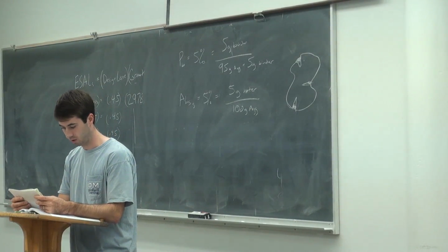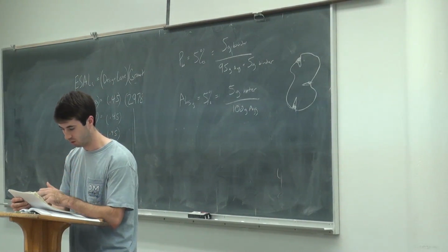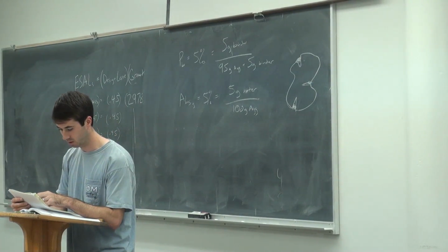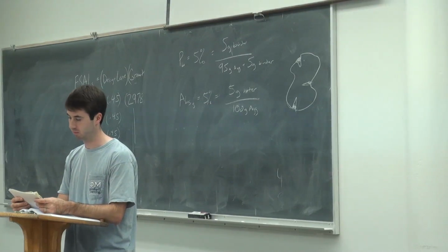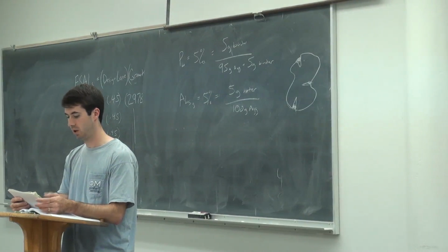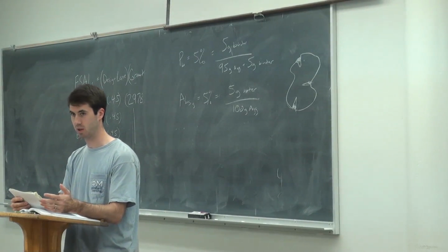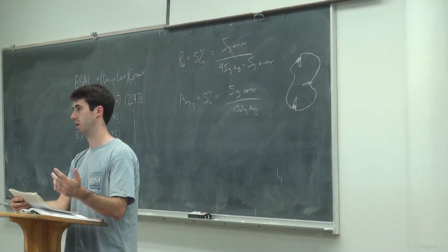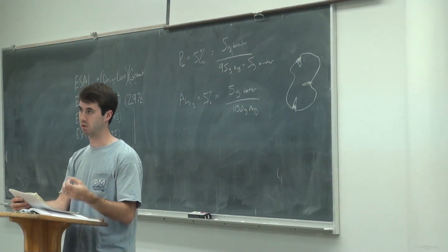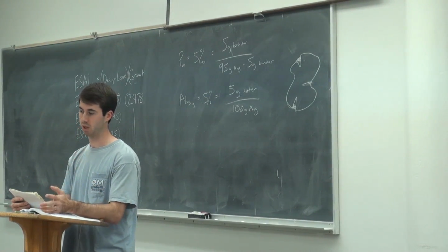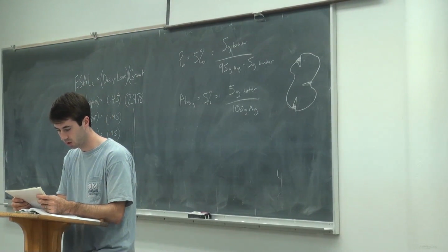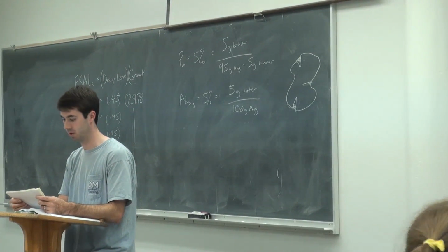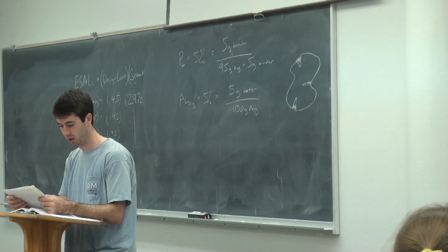The viscosity right underneath that is always running at 135 degrees C, and it has a maximum limit of this 3,000 cP centipoise. All it's saying, and that's for pumpability. They got to be able to pump the stuff through the plant. So if it's too viscous or thick, they can't pump it. So that's what that is. Basically, every binder's going to pass those two things, which is why they go all the way across.